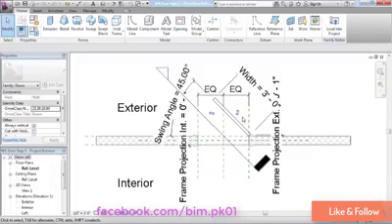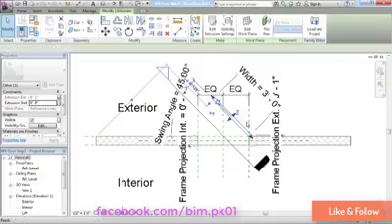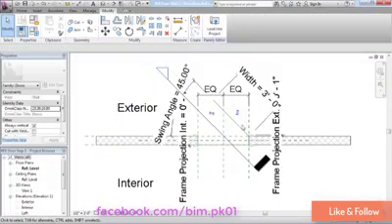The alternative approach that we can use to building the extrusion directly on the work plane is we can nest in a nested family. So to start off with, I'll delete the extrusion, and I still want to keep my reference line. That's going to remain important to control my rotation and other parameters. So we'll keep that reference line. But instead of drawing the extrusion directly on the reference line, we'll bring in a family to use there instead.